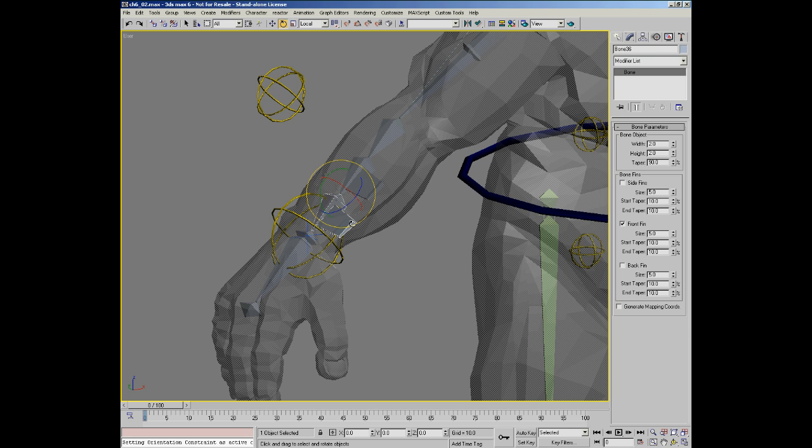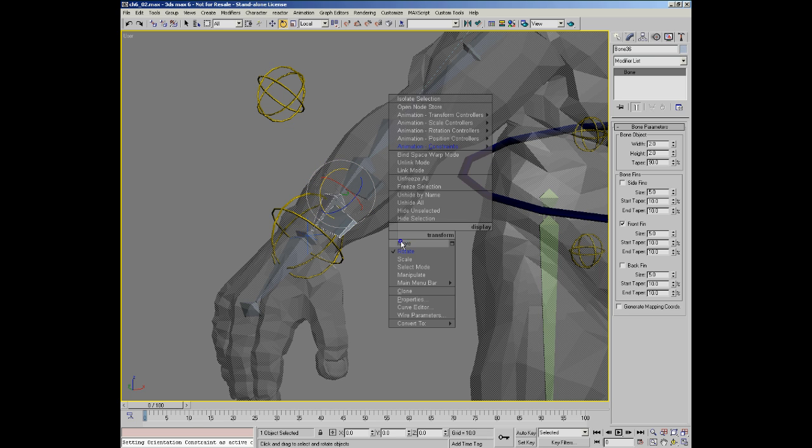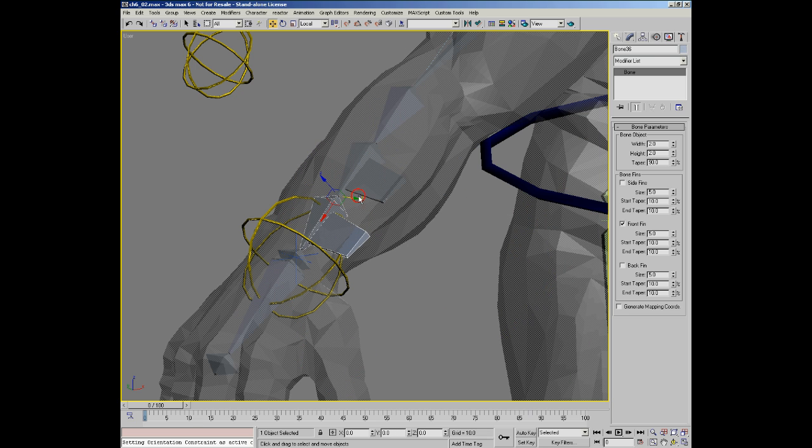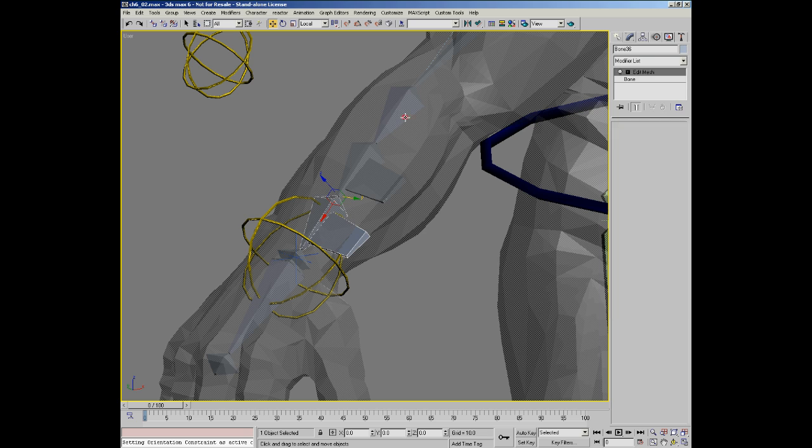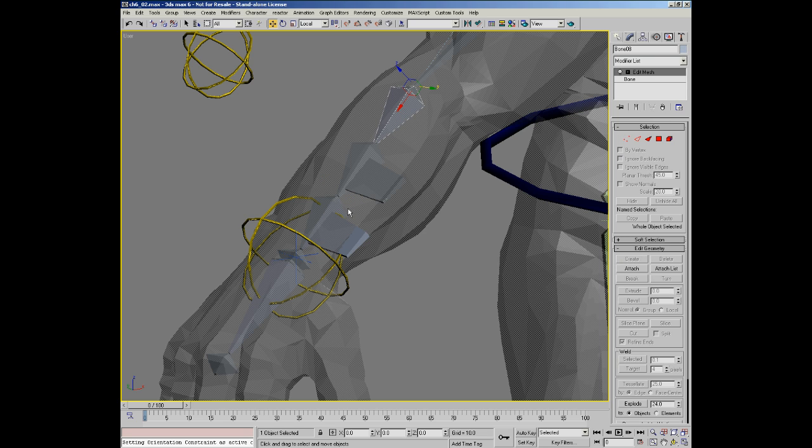The general rule is that the middle axis of the three, XYZ, is the one that will flip at 90. The other two will flip at 180. So if we take a look at the local axis of this joint, Y is across because that's how we originally had set it up.